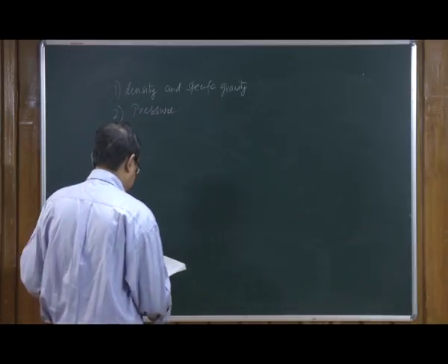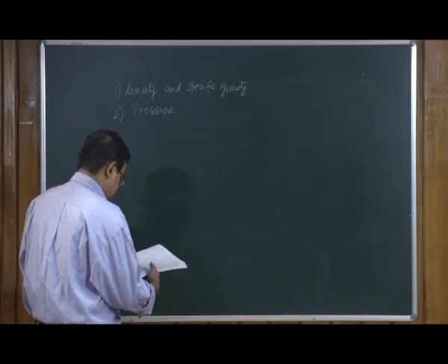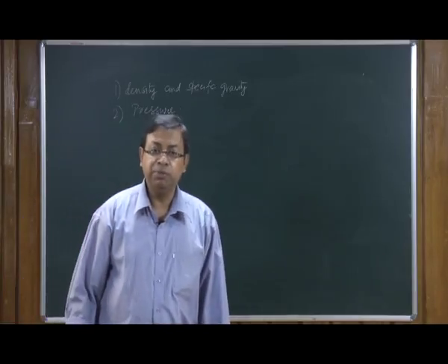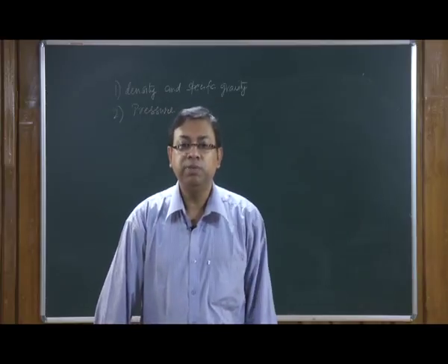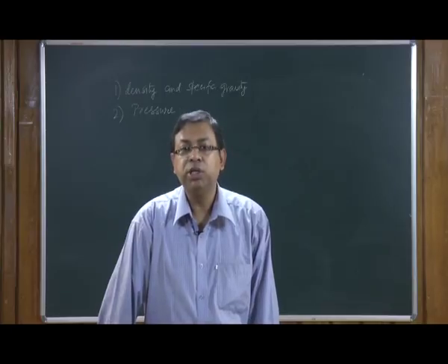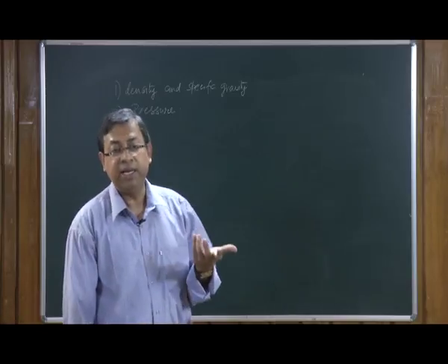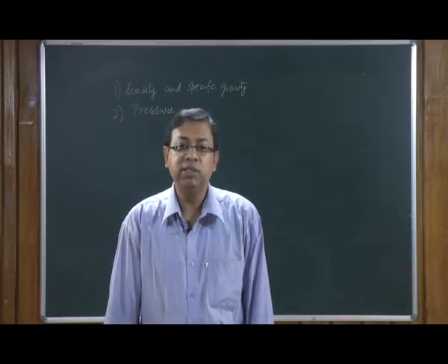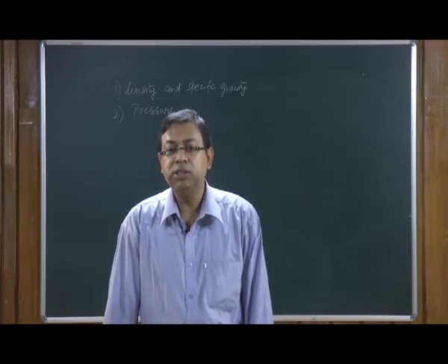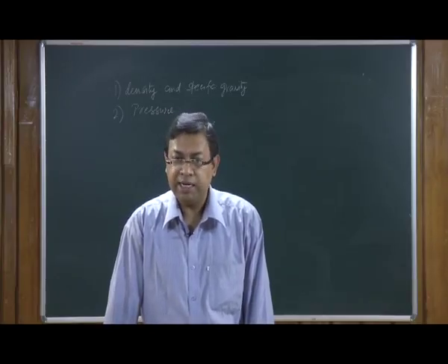So, we have talked about, of course, atmospheric pressure and gauge pressure, and we know that the atmospheric pressure has to be added to the gauge pressure in order to calculate the exact pressure. So, if at some place the pressure is quoted as say 2.7 atmospheric pressure, the actual pressure is 3.7 atmospheric pressure, because 1 atmospheric pressure has to be added.